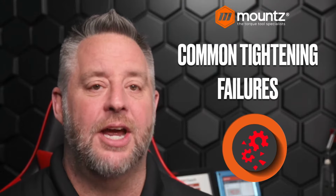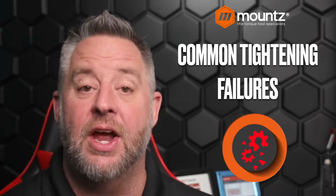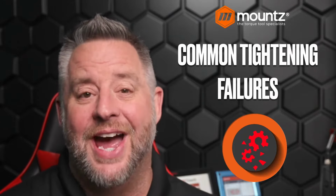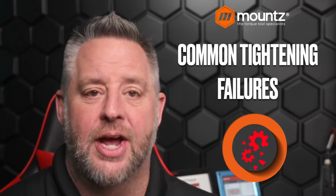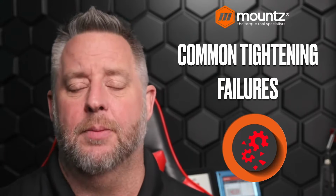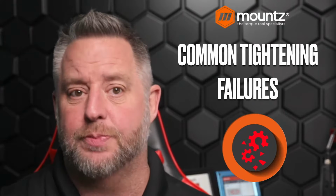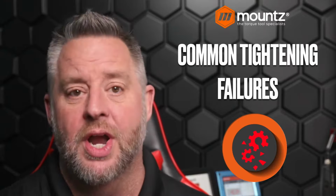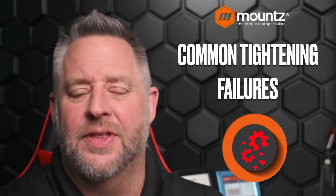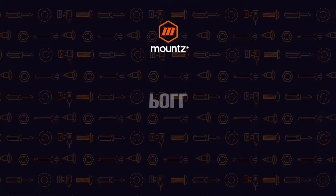And if there's any type of vibration or shock, that can cause that fastener to break and fail, and then we have, again, lost our clamp force. Again, operators not paying attention to what they're doing, not hitting specific fasteners that they're supposed to in a correct pattern or in other types of processes. So these are some of the common tightening failures that we see within the process out there.